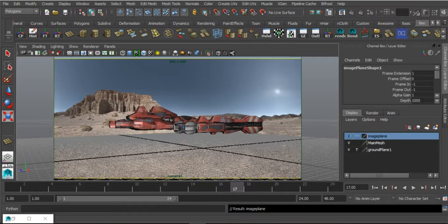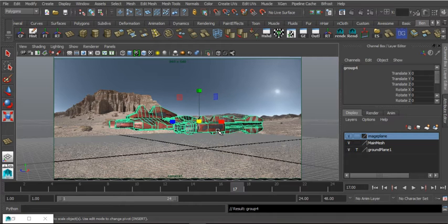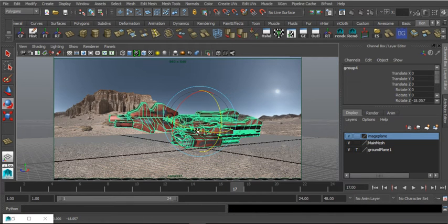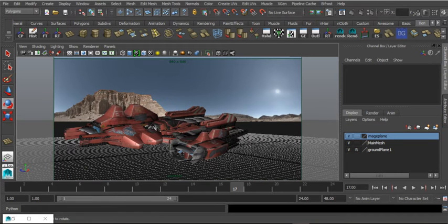I'm going to leave it on for a second, and I'm just going to orientate my geometry into an interesting position. So I'll maybe have it at an angle like this, and that will do. And now that I'm happy with the position of my camera, I'm going to keyframe it to this timeline here, so that if I ever move the camera, I can wiggle this timeline and it will snap back to position.